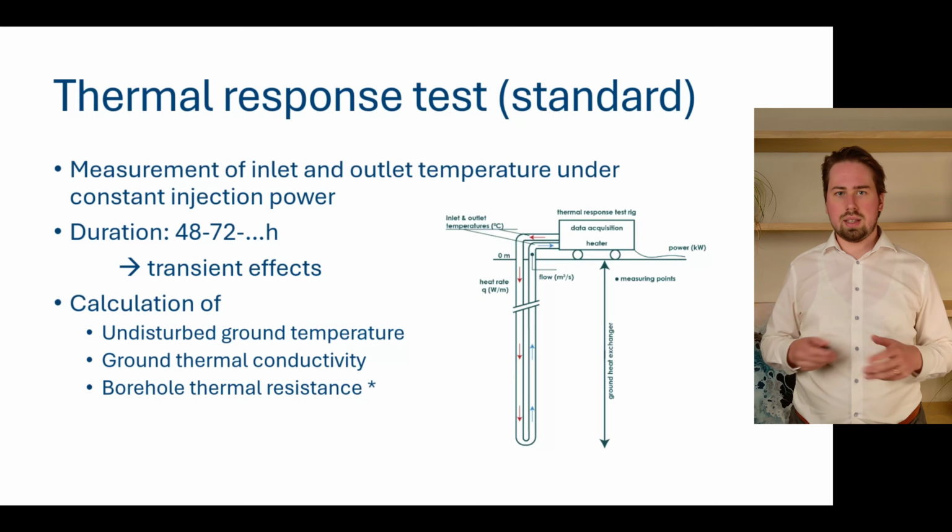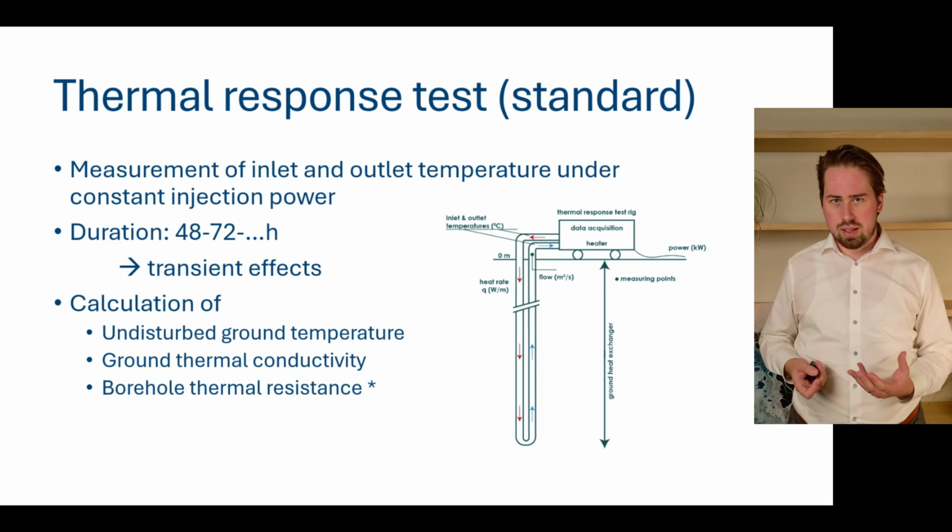And we also said that there are databases for these, especially geological departments in each country or each region has some sort of data for this. But of course, this can change, or there is always some uncertainty on this. Because geology is not that straightforward, it can happen that your own project has a slightly different ground temperature or conductivity. And the only way to know that is by measuring it in situ at the real project location. And this can be done with a thermal response test.